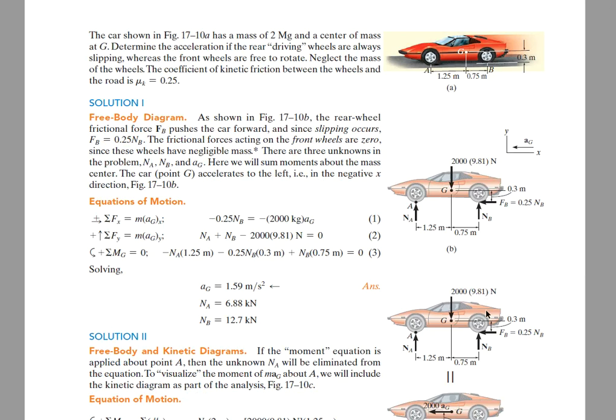So again, there's no rotation involved, but because of the nature of the problem, we're going to see the center of mass being offset from the reduction point, and those mass times acceleration products, negative inertia forces would be correct to call them by other sources, they produce moments.